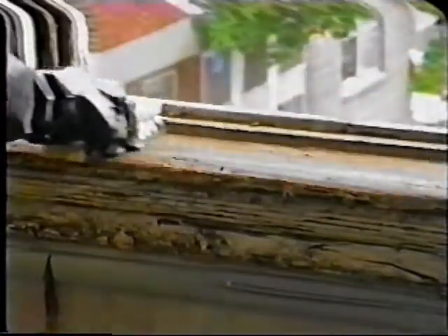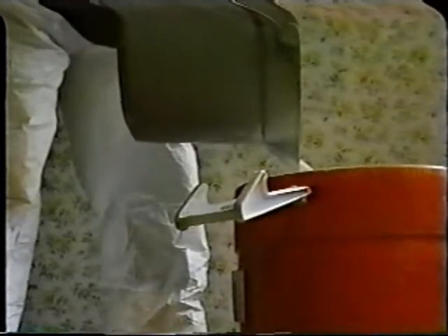After the surface is neutralized, it should be scrubbed with a detergent followed by water to remove remaining lead residue. If the washing process is not thorough, new paint applied to the surface will begin to deteriorate within a few days or weeks. Retrieve the wastewater through wet-dry vacuuming or sponging. This liquid waste contains significant amounts of lead and may need to be tested and treated as a hazardous waste. The solid debris from this entire process is almost always hazardous waste and should be deposited in a watertight and corrosion-proof container and transported to an appropriate waste facility.